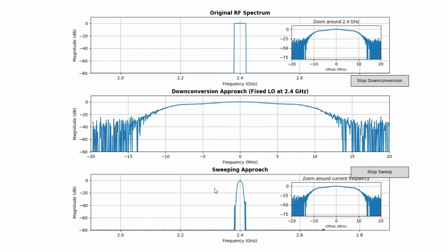This is also something that may complicate the design of the PLL. Usually when we want to have very fine frequency steps, we need to use fractional PLLs, whose frequency resolution or frequency steps are limited by the architecture of that PLL, like how many counters we have or how many bits we have for defining the division, and also how good the phase noise of the oscillator is.